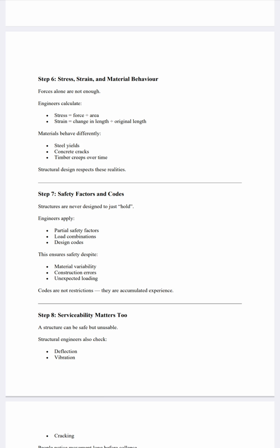And step 6, stress, strain and material behavior. Forces alone are not enough. Engineers calculate stress equals force divided by area. Strain equals change in length divided by original length. Materials behave differently. Steel yields, concrete cracks, timber creeps over time. Structural design respects these realities.